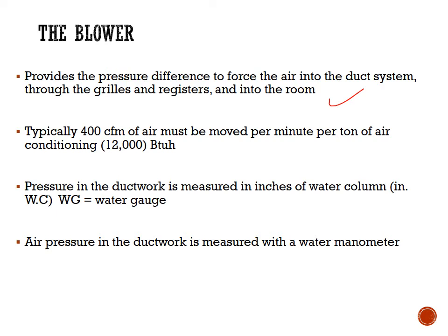And this is another general rule: for 400 CFM we will have 1 ton of refrigeration, which is 12,000 BTUs. So this is the equipment that you would like to have based on the ideal flow rate. It's not always achievable, but it's kind of the best practice number.